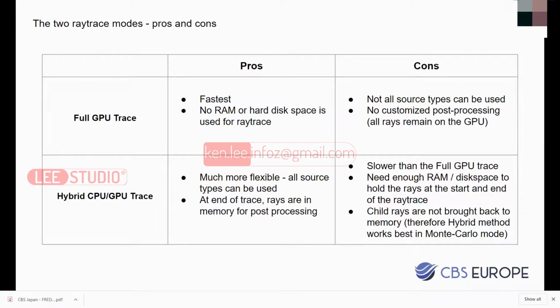So if, for example, the transmission component is 99% and the reflection component is 1%, then on average, every 100 rays that come in, 99 will be transmission and 1 will be reflection. So it's just based on probability, but no rays are created. So that one ray does not create child rays. And whether it becomes a transmission or reflection component is just based on the probability based on the power values of each component. So that's sometimes a very convenient method to use.